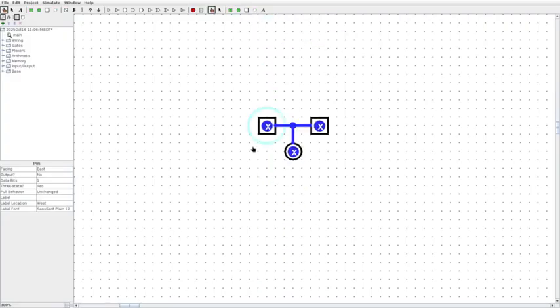Now, something to know about signals in Logisim is that they can have 3 states, well, kind of 4. The first is the undefined state, which is basically saying no signal. Then we have 0, and then we have 1. And the fourth one is an error state, which happens when you have conflicting signals on the same line. Right here we're trying to drive 0 onto this line, but we're also trying to drive 1 as well, and that creates an error.